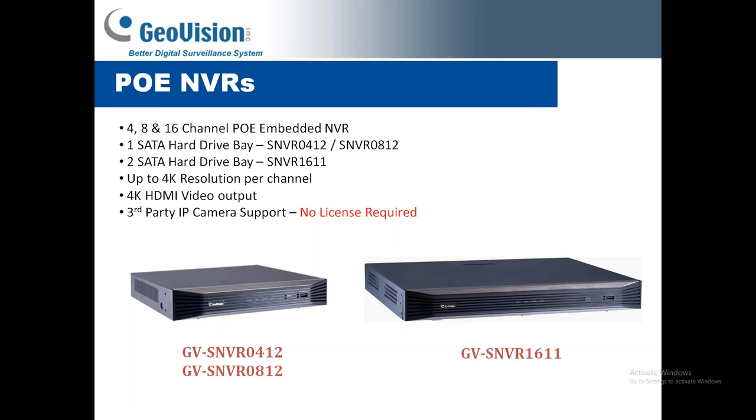We do have some Linux-based NVRs as well. These have a built-in PoE switch. They currently are offered in 4, 8, and 16 channel. Some unique things about GeoVision's Linux-based PoE NVRs is each channel can support up to 4K resolution, and you can put any camera on these units, ONVIF, whether it's GeoVision or third-party, with no license required. So the VMS software, you do have to have a license for, but these units don't run the VMS. They run a more basic view and record software, and no license is required for these units.